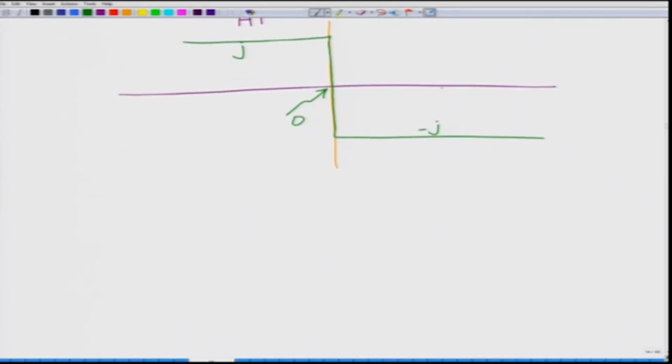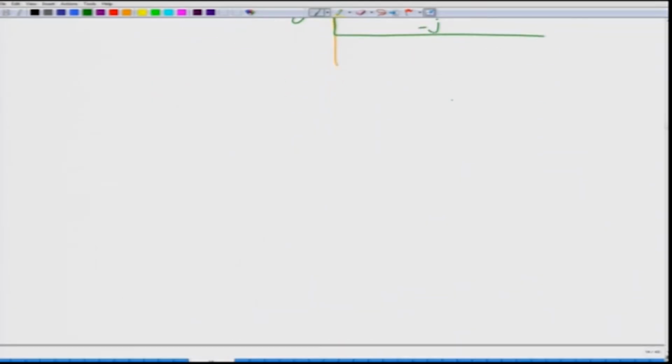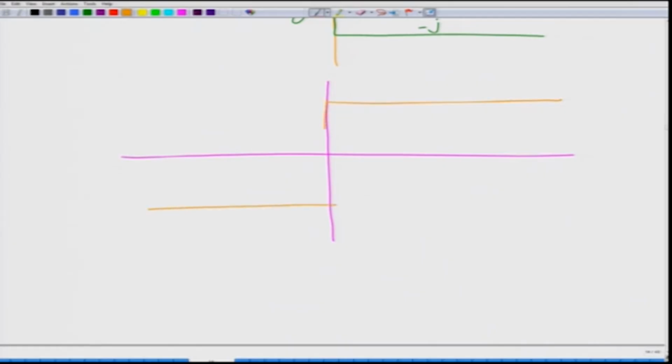And to derive the impulse response of the Hilbert transform, we already said that we are going to use the derivative property of the Fourier transform, alright, and I am going to talk about that shortly. But first, let us look at the derivative of the sign function. Let us go back to looking at sgn of t. It is 1 for t greater than 0, minus 1 for t less than 0, and at t equal to 0, it is 0.